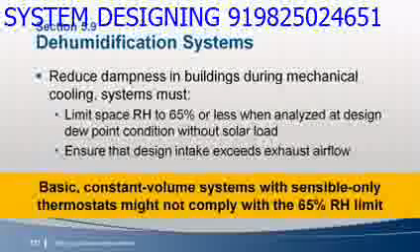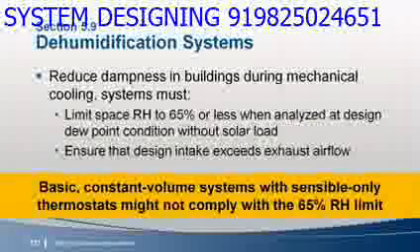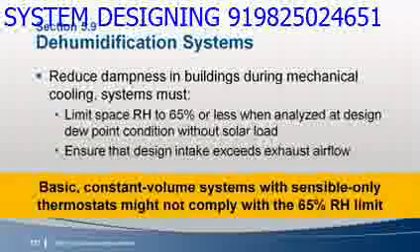In addition to dehumidification, systems must be designed to limit the infiltration of moist outdoor air into the building. Mechanical systems should be operated to ensure positive building pressure during dehumidifying conditions, but the standard simply requires that intake airflow exceed exhaust airflow whenever the system is dehumidifying.